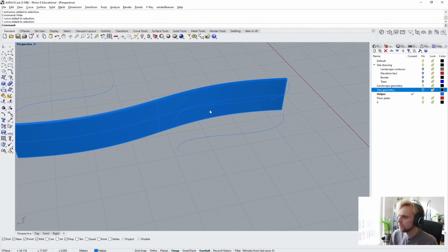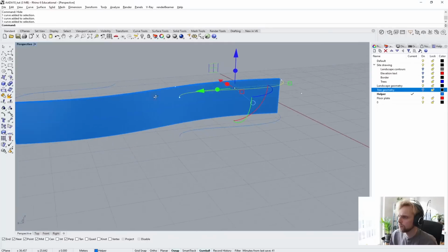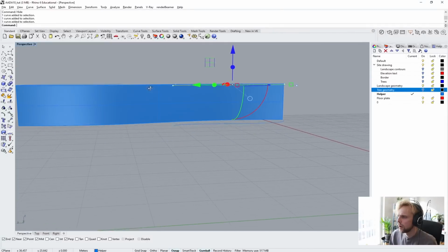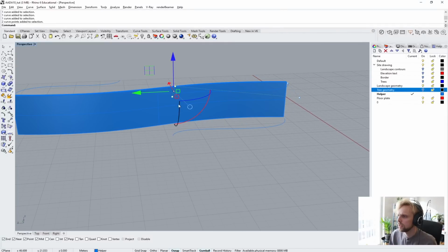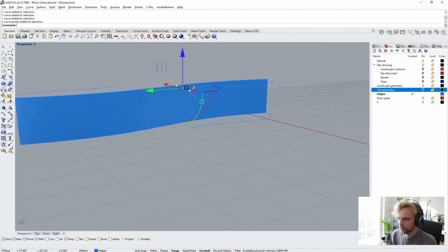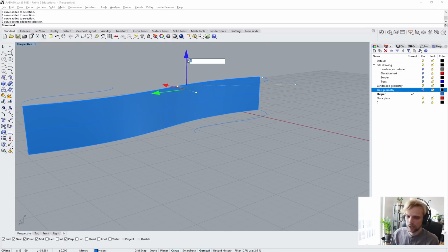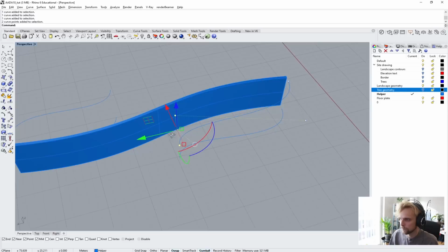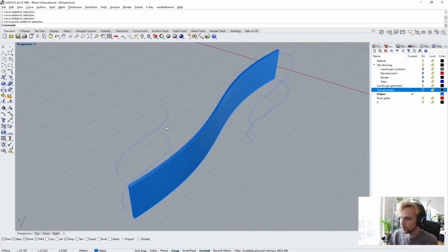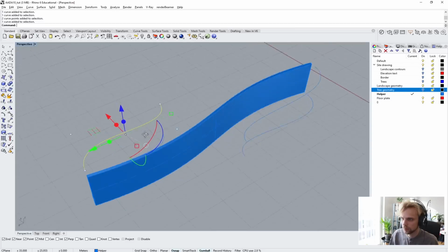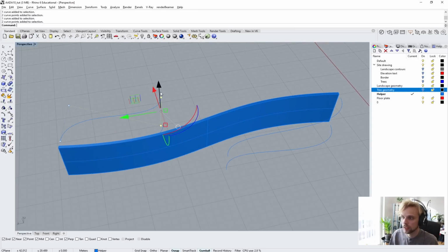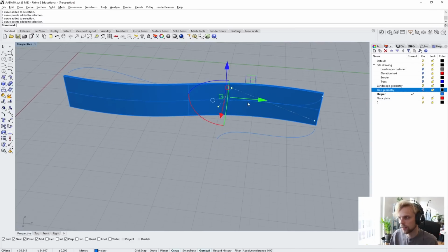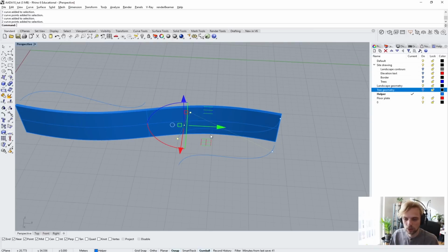And then let me take the top curve here. And actually let me use only these 2 control points and move them down by minus 2.5 meters. Okay? Minus 2.5. And I'll do the same thing with this curve here. These 2 control points. Again, if you don't see the control points, it's F10 or the command points on.